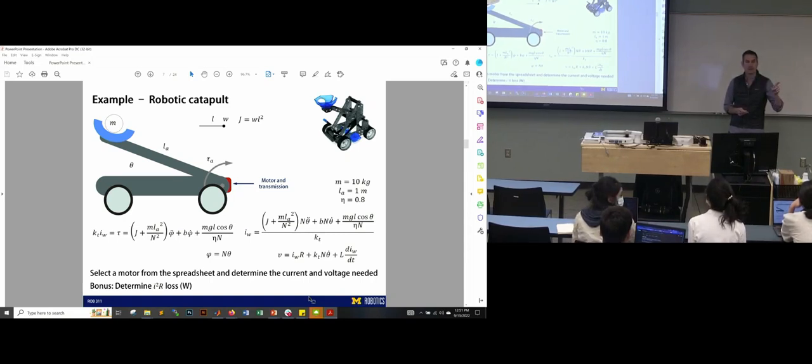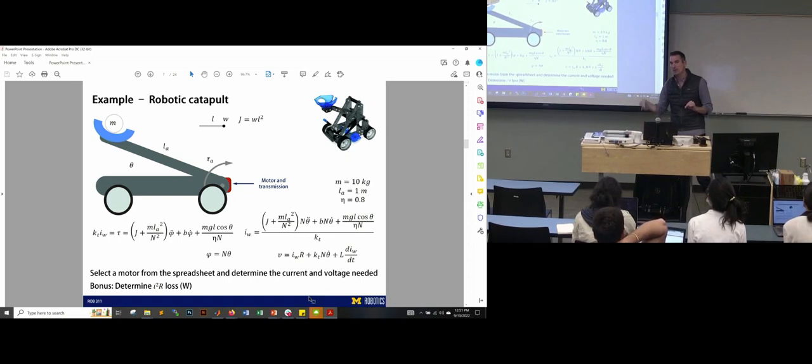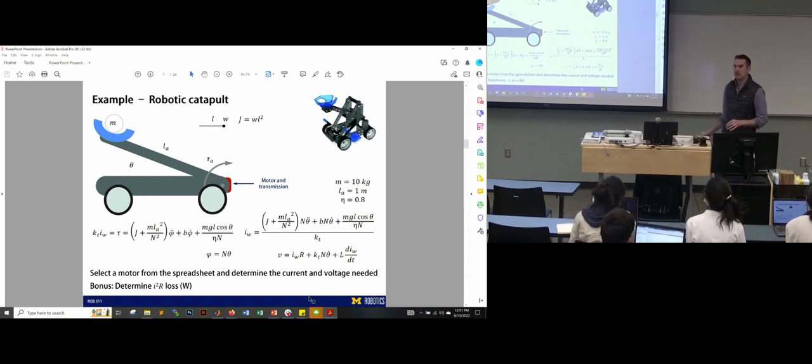Parallel cells? I'm going to say, the current has limitations that are associated with the drive, so we're going to learn about what that is, but that's the circuit component that allows energy to transfer from the battery to the motor, so that drive has its own limits. And then the other way that current comes into play is it heats up the motor. That's what we're going to talk about after we go over lab stuff.